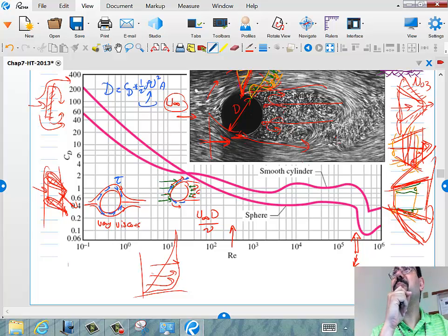So amazingly, if you make the flow turbulent over a sphere or a cylinder, his velocity profile will be more full. He will have more kinetic energy near the wall. He will not separate here. He will be able to persist even longer. And why is this a good thing? Because now the flow is covered by fluid from both sides, a lot bigger area, and the wake region is smaller. So the drag, that's mainly pressure drag, will actually end up being smaller now.